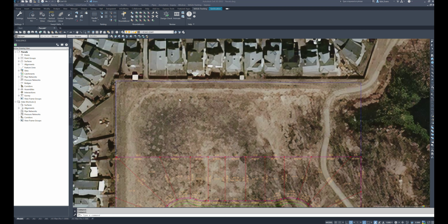In the previous video we started taking a look at our vehicle tracking with regards to semi-trucks and vehicles being able to make corners, and if they can meet the vertical clearance and driving vehicles through intersections. We're going to take a look at another part of vehicle tracking today, specifically the parking command, where we can automatically create parking lots, lay them out however we wish, so it's no longer offsetting lines for designating stall spacing and drawing curbs by hand.